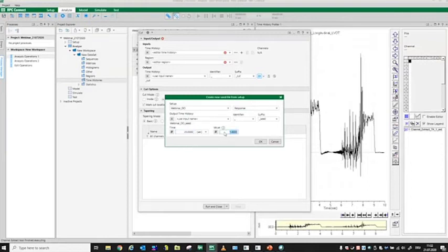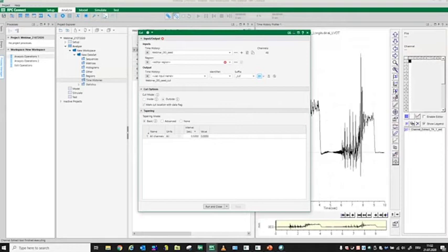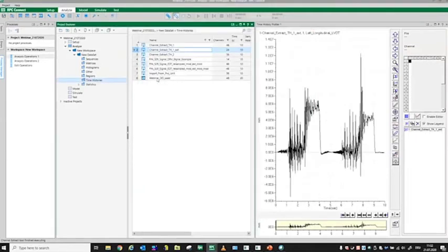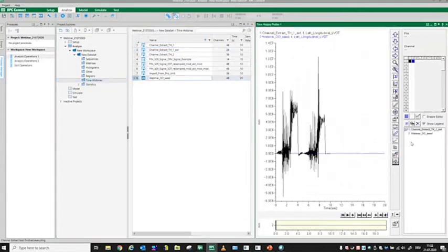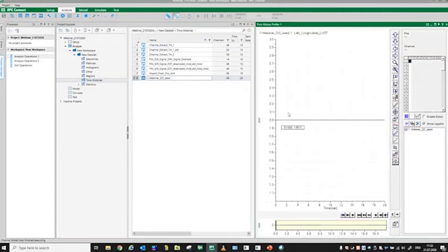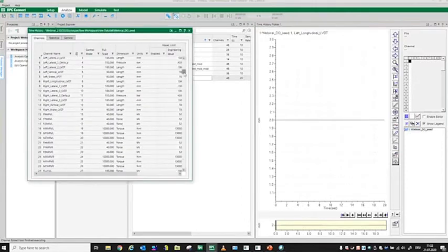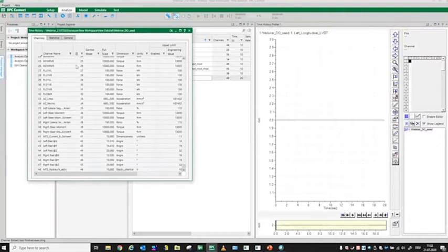And you can even say, okay, you want to have your channels all set to, let's say, 2. So what happens now? If I click on OK and minimize all the windows, I will see a digital I/O. This is called webinar digital I/O because I connected it to my setup, and then seed for the name. You can change the name to whatever you want, but let's see what happens here. If I go into that file and have a look, you see the channels I have are all related to the setup. So it's all the response side we sorted out. This was the populate channel functions I used in the setup in the beginning of the webinar. So it shows my 48 channels.